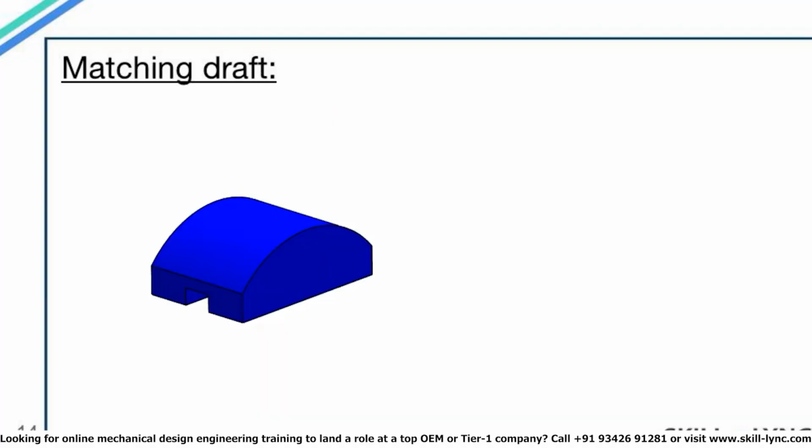So let's go back to the previous model with the 90-degree cut. So if you get a part like this for mold design, you should notice that there is a side groove in the model which has a 90-degree cut. This would in turn mean that if we try to make a mold for this block, then the mold blocks will get damaged over time.